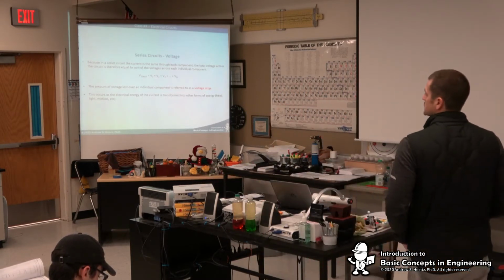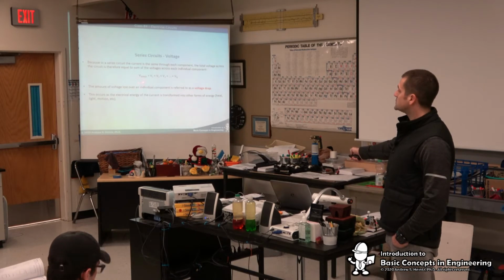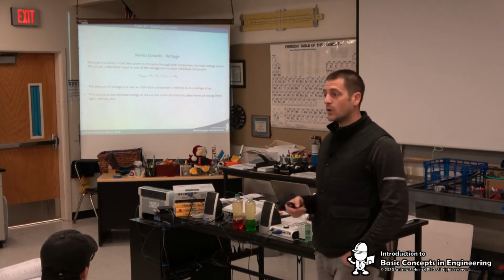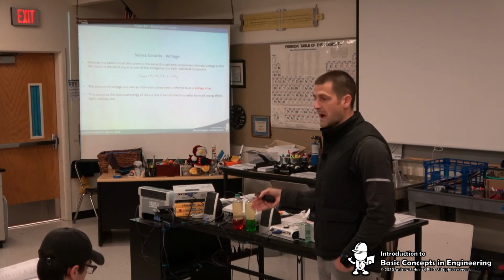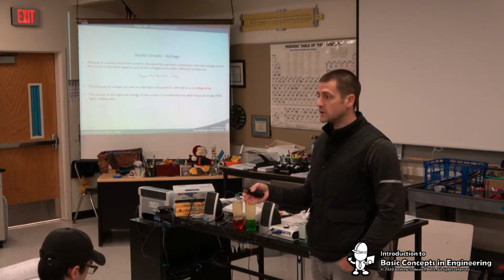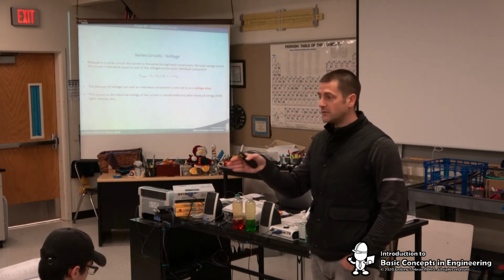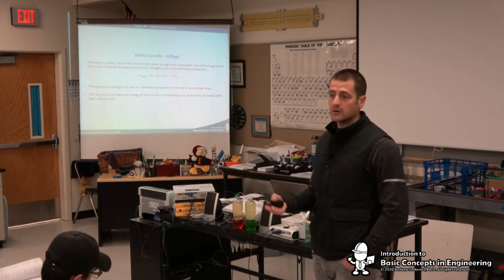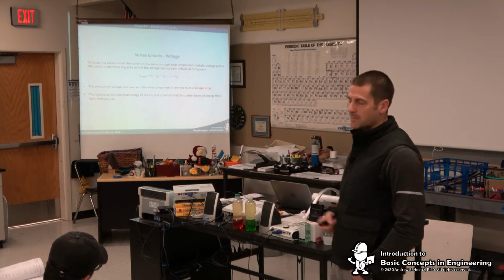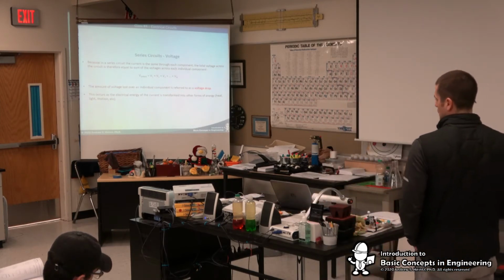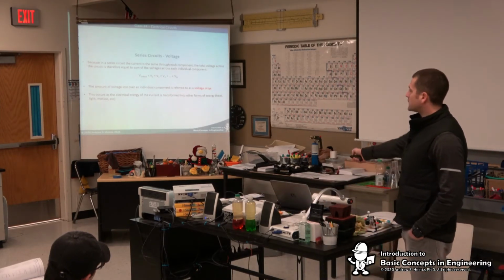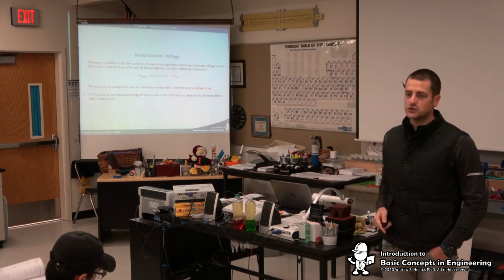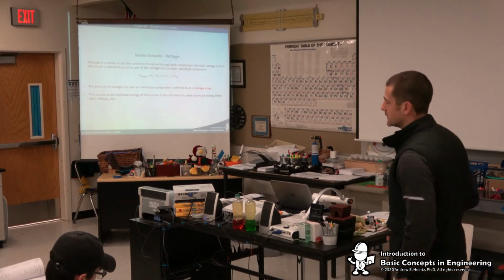So what that leads us to using Ohm's law is that the voltage of the series circuit equals the voltage consumed by each one of those lights. Or individually, that means you can actually go back and start doing your algebra, start doing your math, and if you have an unknown, you can easily solve for the unknown voltage, or the voltage drop across that individual component. Okay? And that brings us to this term. The amount of voltage lost over a single component is called the voltage drop. Okay, that's a term that you will hear ubiquitously in circuits.